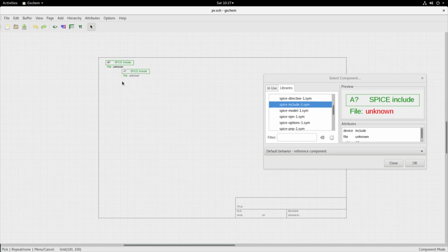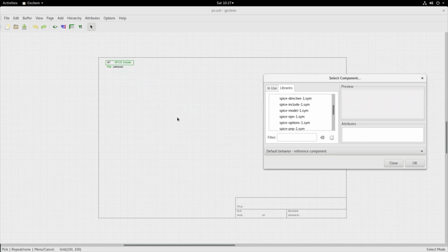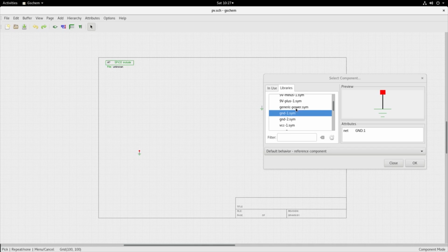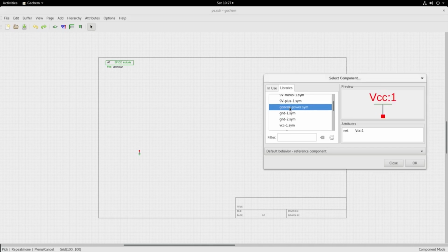You place that here. I will explain about that a bit later. Then we will choose the Power Rails library, and there we need two important symbols. One is the ground symbol, without which the simulation will not proceed, and then the generic power symbol. It is a label. We need to label the nets, so let us place that here. I will explain that later again.